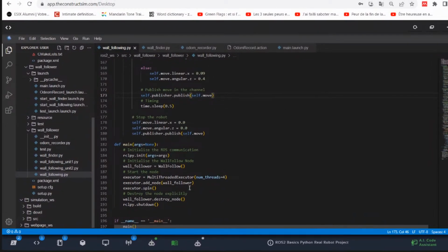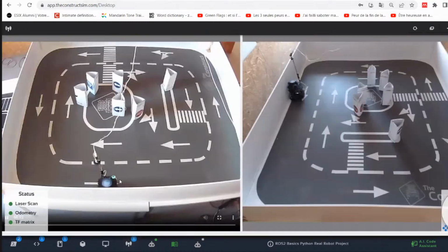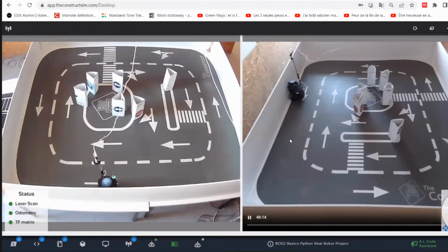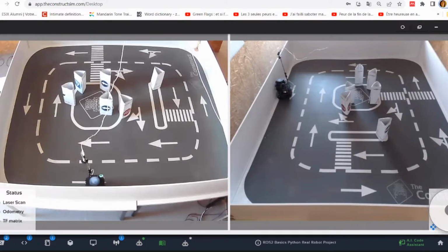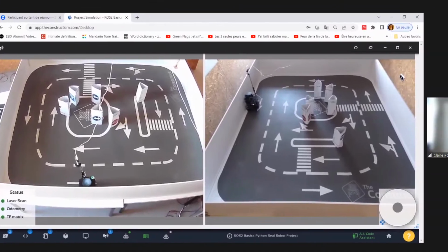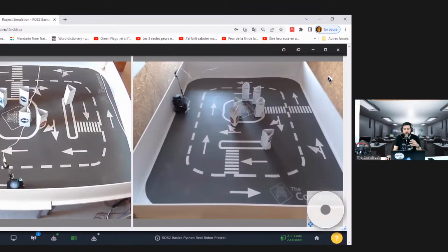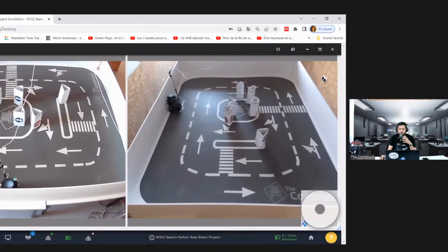I'm curious. Is the robot still moving? Now I think it's ran into a wall, fortunately. Yeah, this is the problem, I would say, due to the swing and the communication as well, and different parameters. In that case, the robot will move, I would say, step by step towards the wall. And this is also because the odometry will start drifting more and more. So it makes sense that after a long time it would do that.